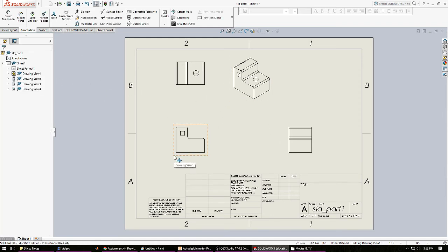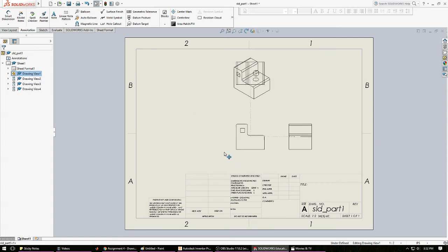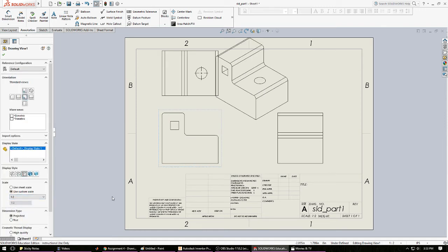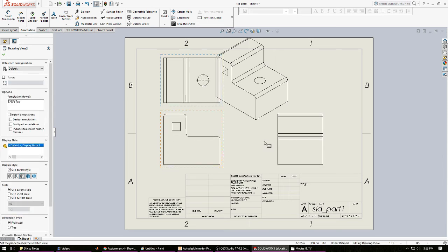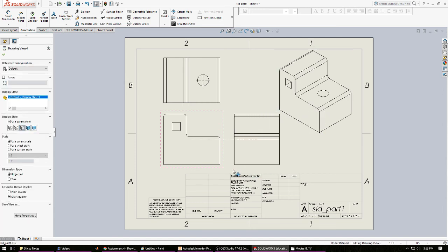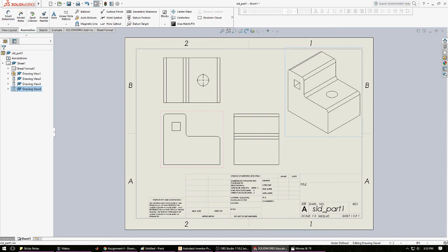Now, if you notice, as I change where the front view exists, it will change the alignment because everything needs to be aligned for these drawing views to work. Maybe I will do a 1 to 2 ratio. Yeah, I can fit that. That'll work. All right. So what we have here, the isometric view doesn't apply to this rule, by the way. It kind of does what it wants because this is mostly to get an idea of what it looks like. So you always have 3 orthographic views and then an isometric view to kind of garnish the thing.